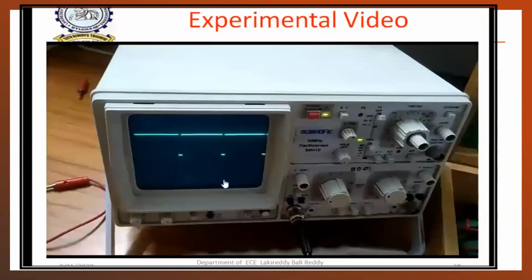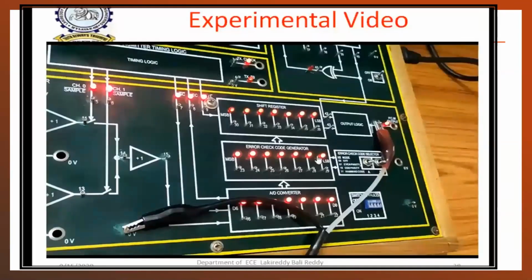If you observe the direct output for this analog signal, since the analog amplitude has a number of samples, we are getting a number of bit sequences, one after the other. So there is a large bit sequence. For example, the sample signal has 1000 samples. For each sample value, 7 bits are transmitted. For all those 1000 sample values, these 7 bits are transmitted 1000 times. So totally 7000 bits are transmitted at the PCM output.